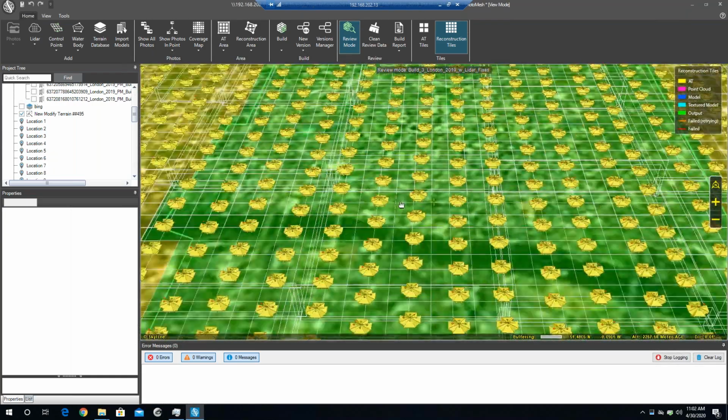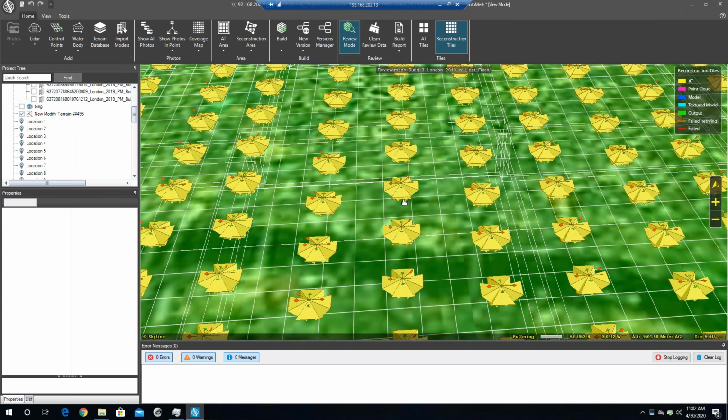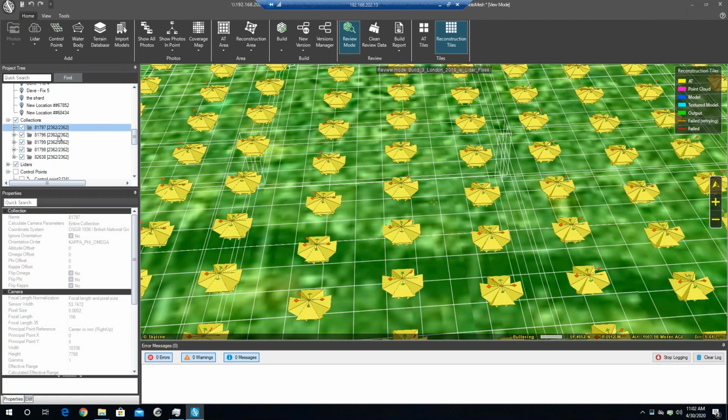The icons that we're looking at are the 5 camera systems, which is a nadir and then 4 oblique cameras. PhotoMesh has the ability to import the data with the raw airborne GPS IMU information, and then perform the entire aerial triangulation process and everything that's necessary to get the images to align to one another, as well as align to the LiDAR if it's necessary to co-register the 2 data sets using some control points.